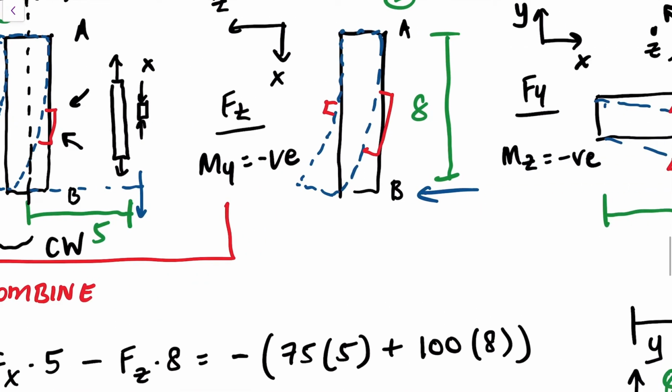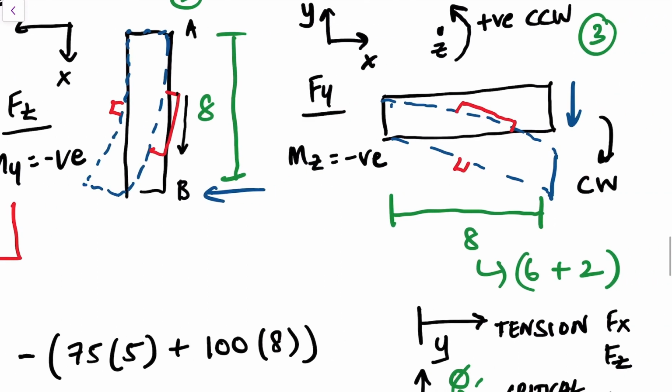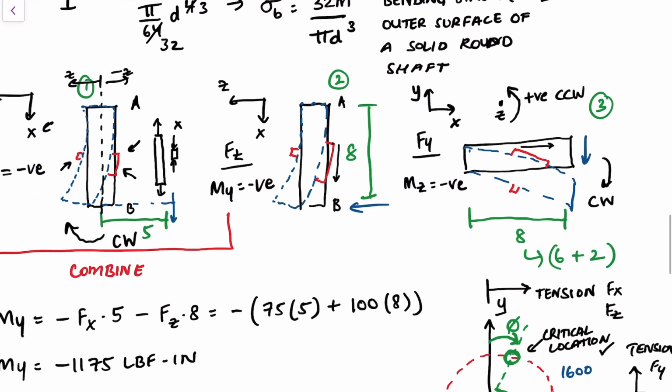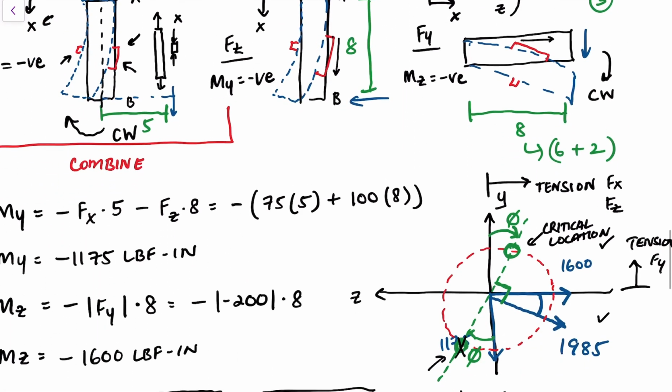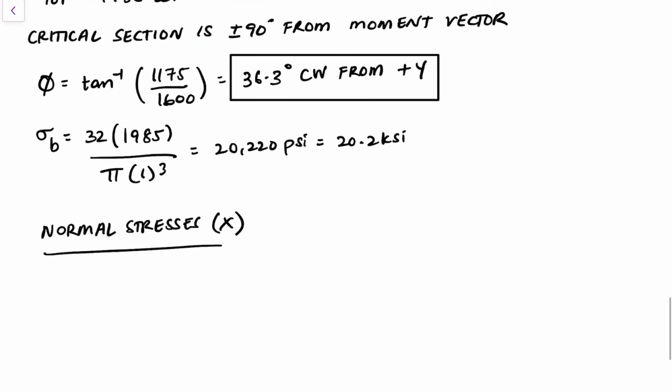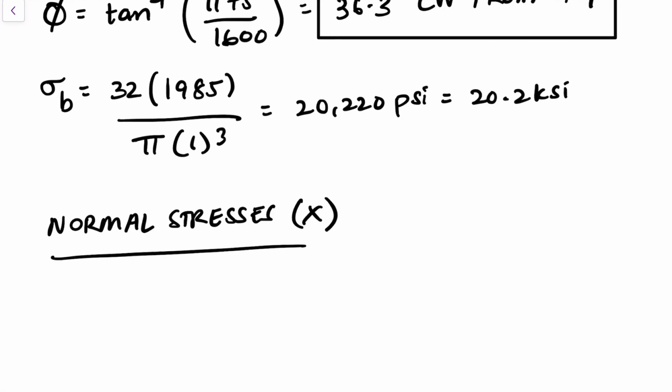Similarly over here, it's stretching in the x or compressing in the x, and even over here, it's compressing and stretching in the x. So effectively, it's a normal stress, where the compression or elongation is perpendicular to the cross-sectional area. The normal stresses are in the x, and so was the axial stress.